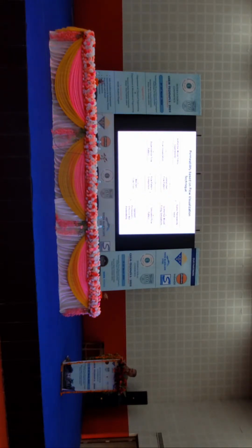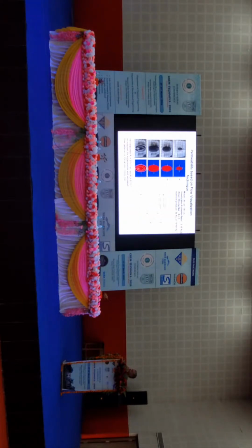So that flow front reach as a function of time is called the flow pattern. The experimental flow pattern is collected, and the same conditions are mimicked in the simulation environment by varying the permeability value. For every permeability value I guess, I collect a simulated flow pattern and compare it with the experimental flow pattern. Whichever guessed permeability value gives a match between the experimental and simulated flow patterns will be taken as the effective permeability value. Next slide, please.